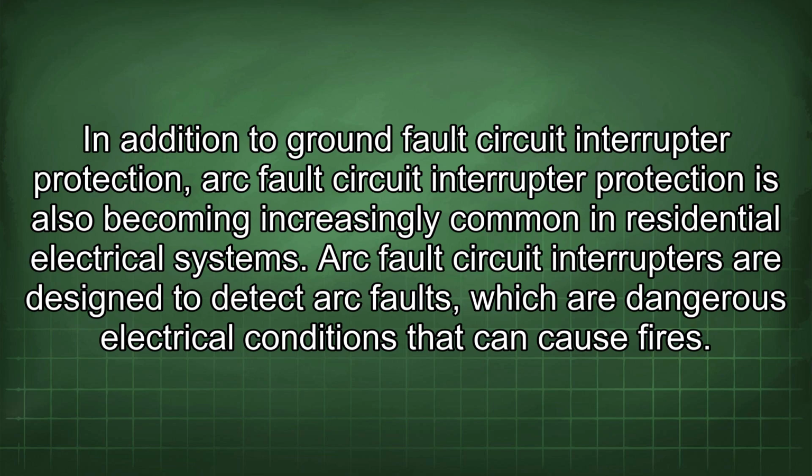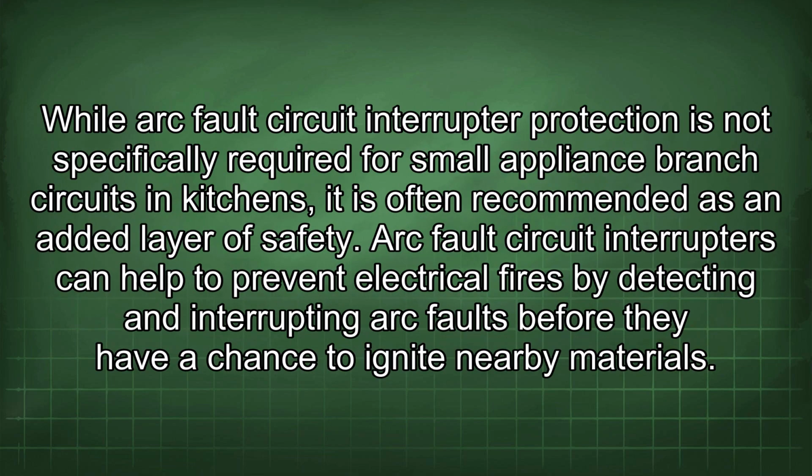In addition to ground fault circuit interrupter protection, arc fault circuit interrupter protection is also becoming increasingly common in residential electrical systems. Arc fault circuit interrupters are designed to detect arc faults, which are dangerous electrical conditions that can cause fires. While arc fault circuit interrupter protection is not specifically required for small appliance branch circuits in kitchens, it is often recommended as an added layer of safety. Arc fault circuit interrupters can help to prevent electrical fires by detecting and interrupting arc faults before they have a chance to ignite nearby materials.